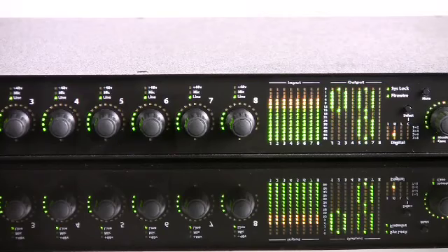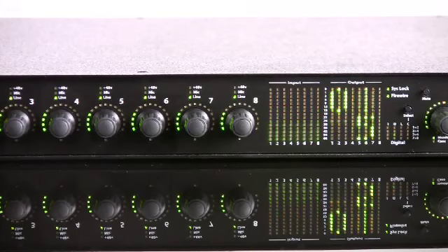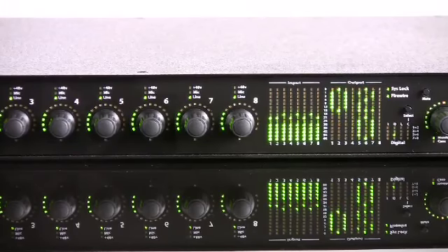The encoder resolution is software selectable. The default is 1 detented click is 0.5 dB. Pushing in on the encoder and turning changes by 3 dB. These values can be changed to whatever you'd like in the Mio console software. Another feature is that when a channel goes into overload, the channel's entire meter and encoder LEDs will turn red to give you positive indication that you're clipping.